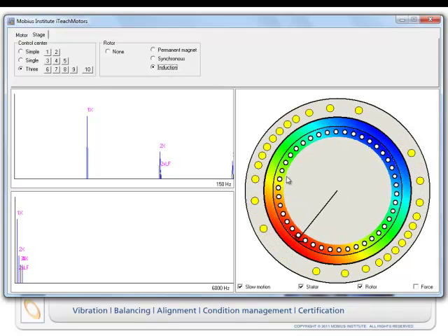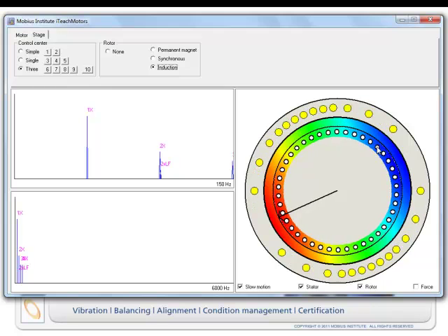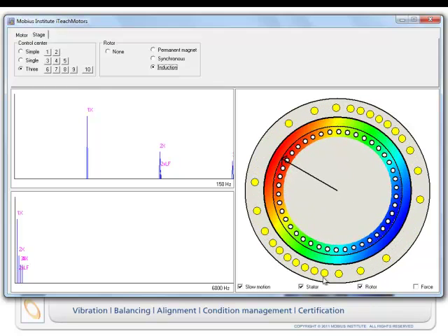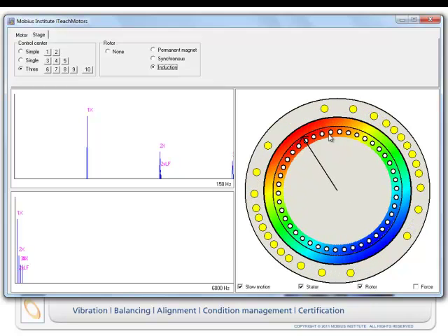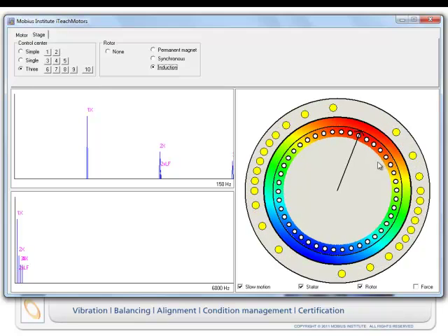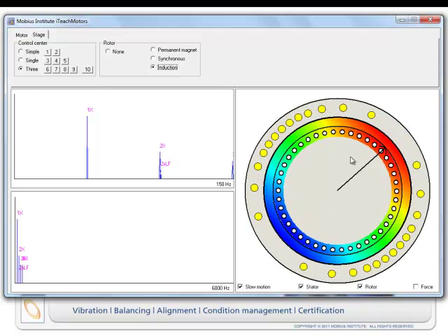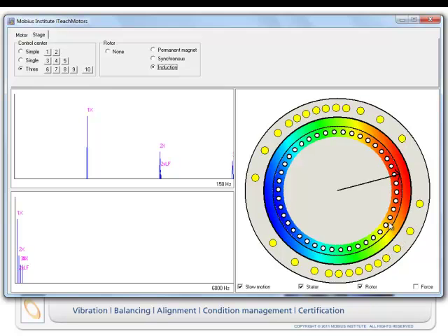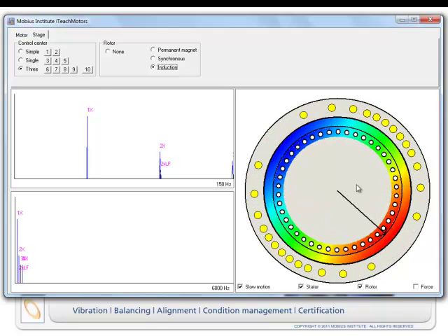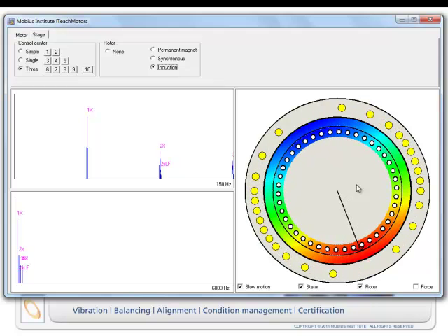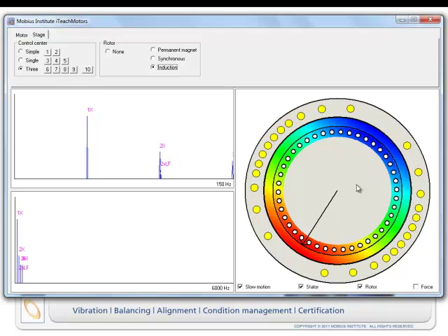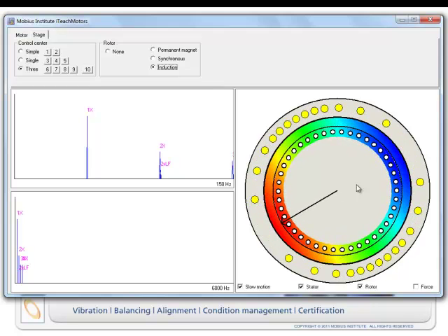And then finally, of course, we get into the induction electric motor. In this case, each of these are the rotor bars, and they're not powered, but when you start putting this rotating magnetic field, the current is induced in these windings. That current generates a magnetic field, and it starts to chase the magnetic field. But it can't catch it, because if it was turning at the same speed, then there would be no current induced into those rotor bars, and therefore it wouldn't chase the magnetic field and it would slow down.